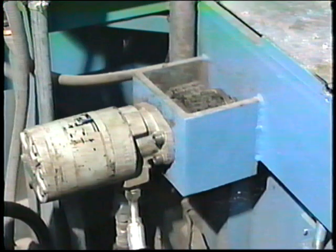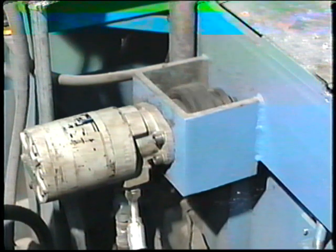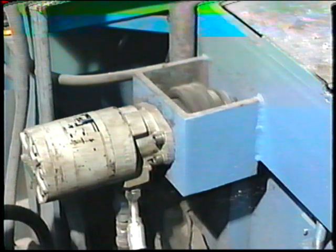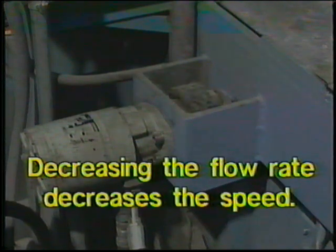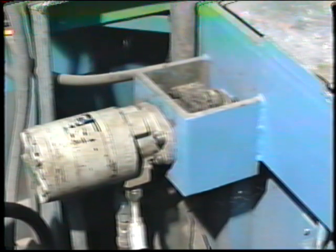A similar relationship exists between flow rate and speed. If flow through the motor increases, then the vanes will turn faster, and the speed of the shaft will increase. Again, this direct relationship between flow rate and speed is the same for all hydraulic motors. Increasing the flow rate will increase the speed, and decreasing the flow will decrease the speed, as long as the size of the motor remains the same.